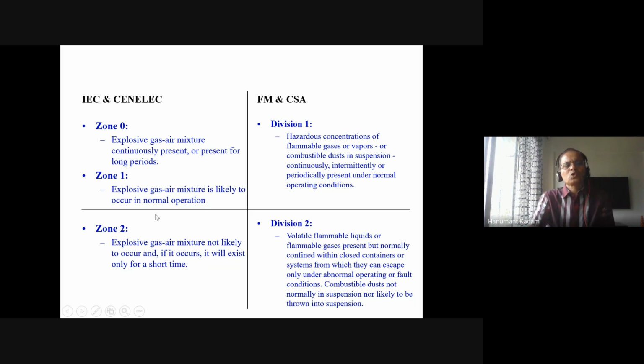So you can see that zone 0 and zone 1 areas are very crucial, and there you need to take care of transmitter enclosures and electronics of that category. For example, explosion-proof enclosures, electrical wiring or fittings are of that category. Even on the DCS side, all cabling, junction boxes, termination, everything is of Ex category. You need to have approval from the manufacturers, a certificate from the manufacturer, and all governing or compliance related organizations and government authorities check these certificates.